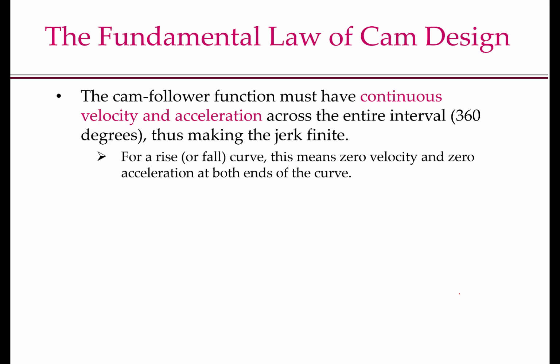This intuitive discussion leads us to the fundamental law of cam design, which states that the cam follower function must have continuous velocity and acceleration across the entire interval, thus making the jerk finite. For a rise or fall curve, this means that there should be 0 velocity and 0 acceleration at both ends of the curve. Why? Because we are moving from a low dwell to a high dwell, or a high dwell to a low dwell, or we are moving from a stationary position to another stationary position.